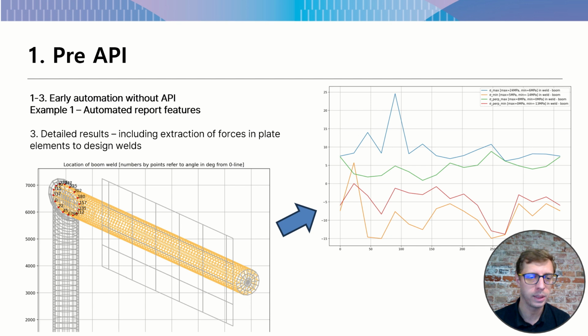Also, while doing this, I developed tools for designing welds between steel elements. So this was all detailed to design the weld that was going around the circumference here. The problem with the 45-degree cut here is you don't have a nice clean situation where you could just use a butt weld or just use a fillet weld. This is a weld that is essentially somewhere between the two types.